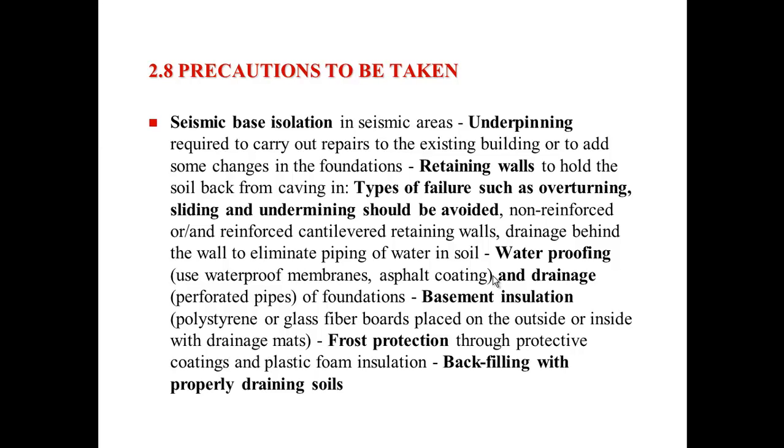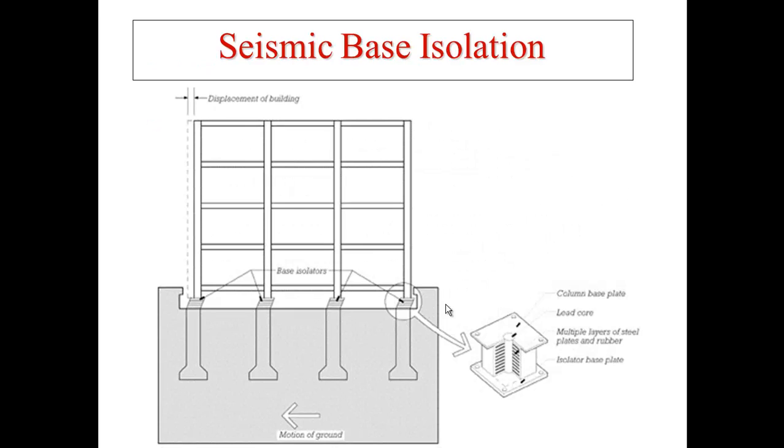Seismic base isolation is used in areas where there could be some earthquake activity, any type of area where the earth may shake by itself. And not to say we haven't had earthquakes up here, but in large buildings the foundations are constructed with what are called base isolators. These are basically steel plates top and bottom with layered rubber-type material in between, so it actually allows the building to move on top of that foundation without causing any structural damage.